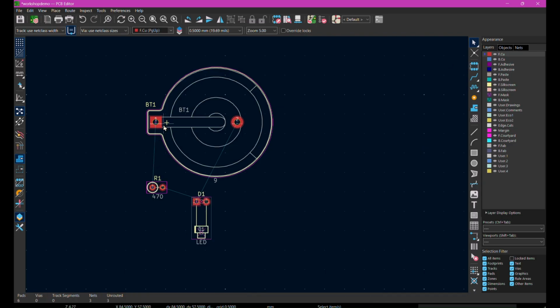And then the next thing we're going to do is actually make the connections onto this board. So right here, we have forward copper, and then you have backwards copper. So if you want your connection line to be on the front of the PCB, you would do forward. But if you want it to be on the back of the PCB, you would do backwards copper. So I'm just going to have all of this be on the forward. And you're going to click this button, and you're just going to start drawing these connections, and it highlights it for you so you can see where you're placing your connection lines. And then I'm just going to do this one in the back.